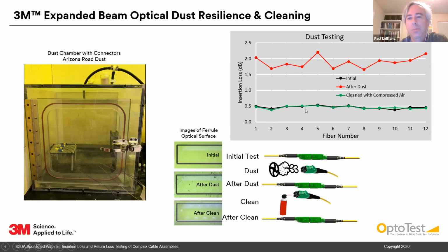And in this example, the insertion loss was returned back to its original value. And so this shows the effectiveness of compressed air cleaning, as well as the benefit of an expanded beam nature being much less sensitive to dust.